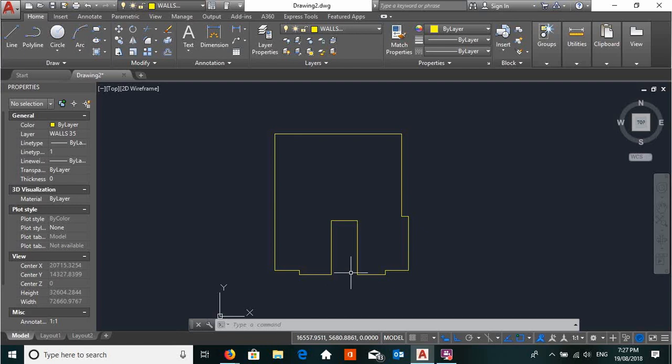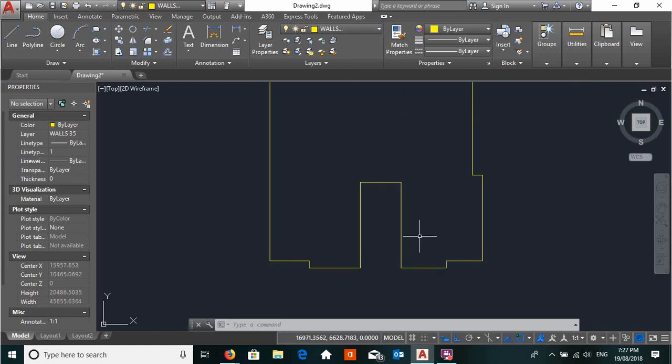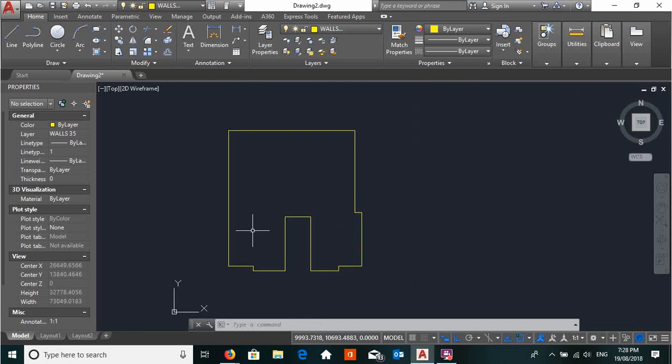All right, so just bear in mind that there is different thicknesses for exterior walls, either being double brick or using a different finish such as Hebel. So your wall thicknesses do change, so just make a note of that. So with this one, it's definitely brick veneer, so we're basing it on those default distances. Okay, now that I've got my outer walls, I am wanting to offset that.